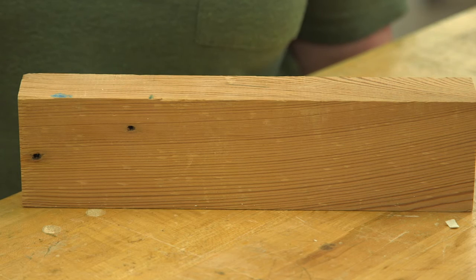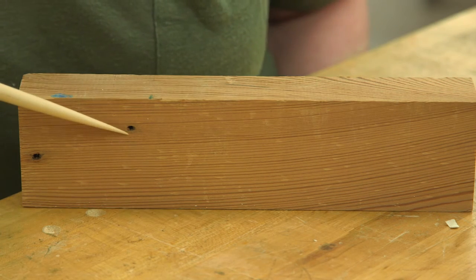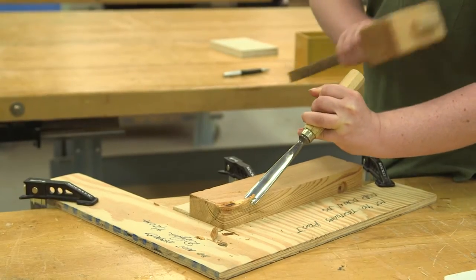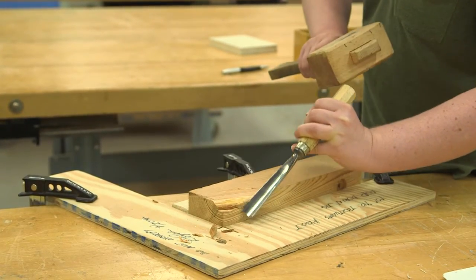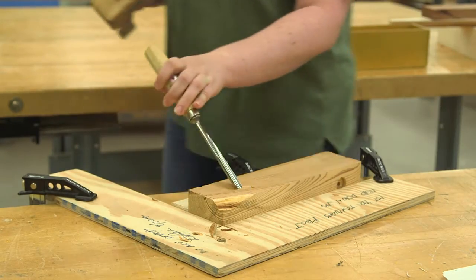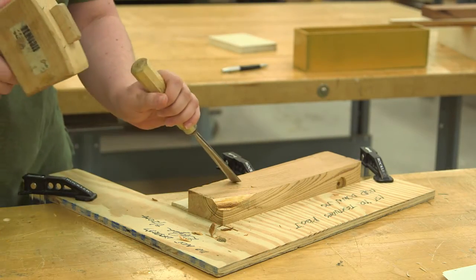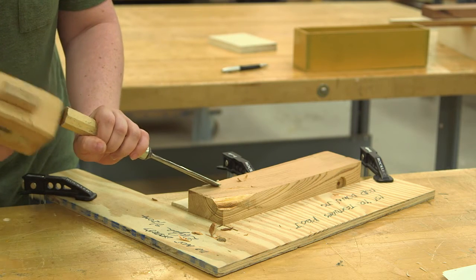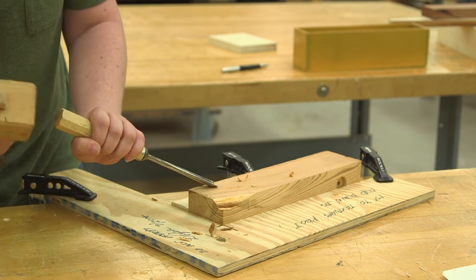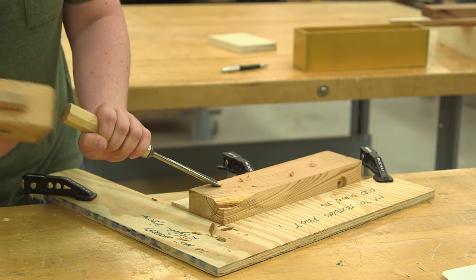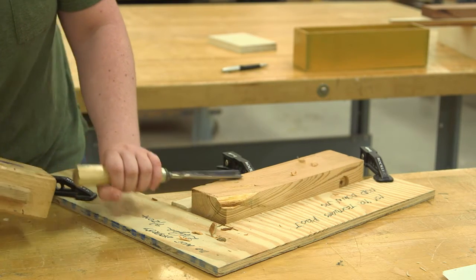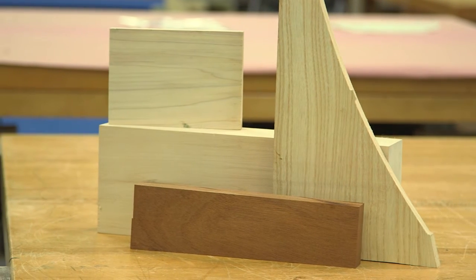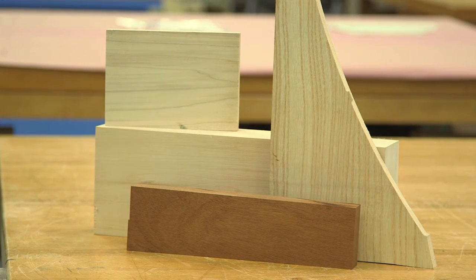You want to carve in a downward direction onto the parallel lines of grain. If the wood seems to be tearing and your tools are sharp, then you're probably carving in the wrong direction. Turn around and carve in the opposite direction. In some cases, a practice piece is helpful, particularly if using unfamiliar material, an unfamiliar tool, or making an unfamiliar cut. The hand carving tools are meant only to be used with wood.